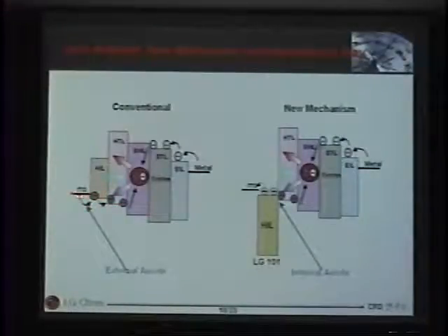So when you treat the ITO with oxygen plasma and make the work function of ITO high, then the work function moves in this direction. So it will reduce the injection barrier from ITO into the hole injection layer. That's the reason why everybody wants to treat the ITO with oxygen plasma.